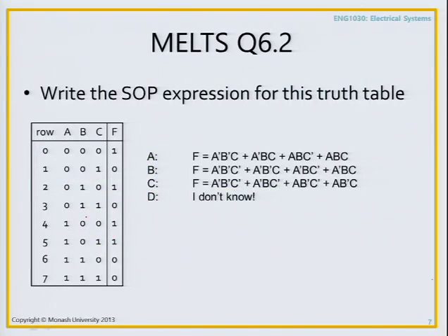Yep, so when there are fewer zeros on the truth table than ones, you would use what? Product of sums. And if there are fewer ones on the truth table, then you would use sum of products, if you wanted to use fewer gates. Does that make sense? Because for product of sums you need a gate per 0 row, and for sum of products you need a gate per 1 row. So whichever is fewer is the one you would like to use.